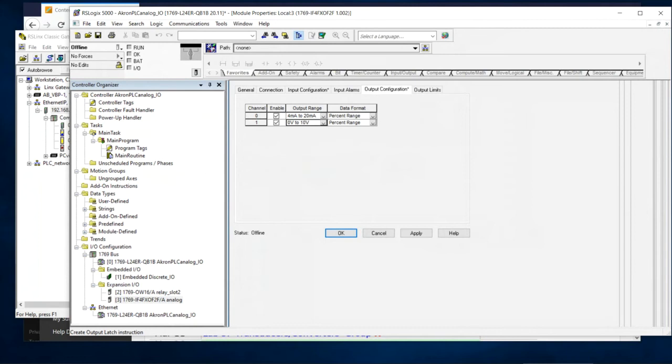All right, and so we have our outputs here, which is just a percentage. Now, the thing is, a percentage, what they do, they don't go from 0 to 100% because it's an integer value, and they want to give you more options. So what the percentage range is actually going to be is it goes from 0 to 10,000. So what they do is they basically give you 2 more decimal points for more accuracy.